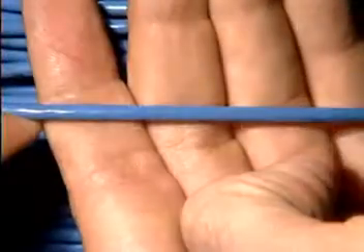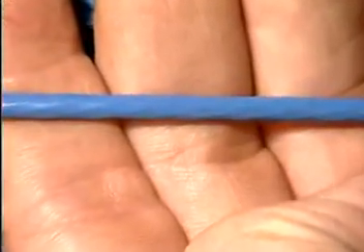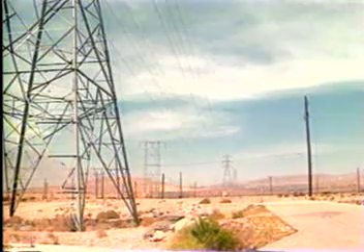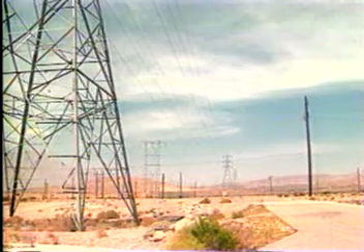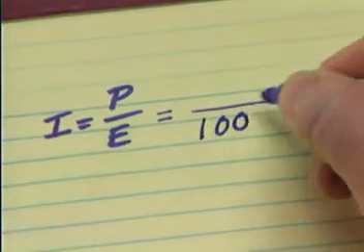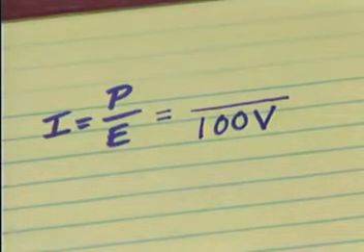While a conductive wire is thought of as having almost no resistance, it does have some resistance over miles and miles of wire. This cumulative resistance is enough to cause a voltage drop over the resistance of the wire itself. Let's look at a mathematical example which compares the power loss of AC and DC during transmission. Use the power formula I equals P divided by E.